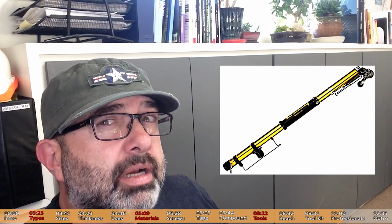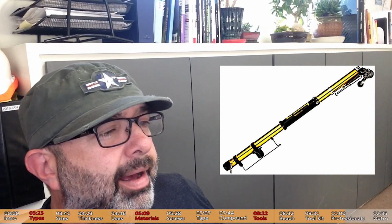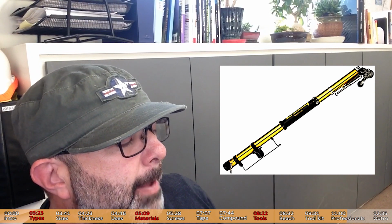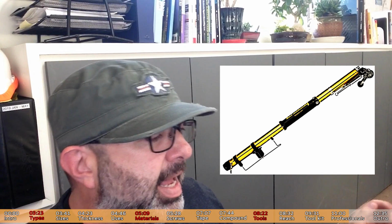But besides that, they also have special tools, and those tools are the ones that are used to tape. They have one that they call bazooka. The name is like a loving name they gave to it because it looks like a bazooka, but it's a taping pole. It's an automatic taping pole that muds the tape and applies the tape at the same time and cuts it exactly at the right spacing.